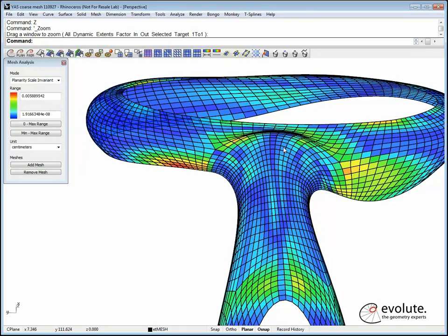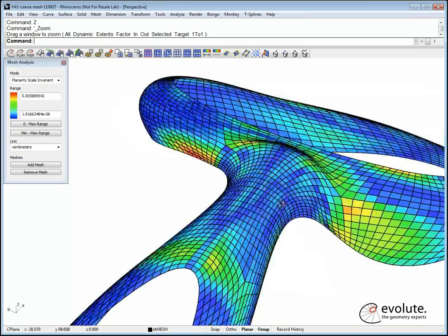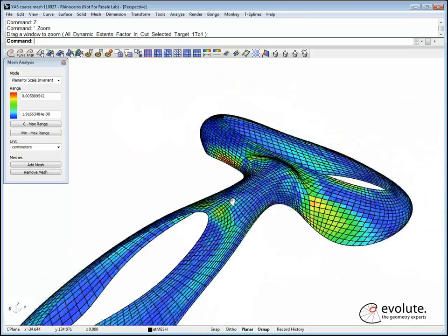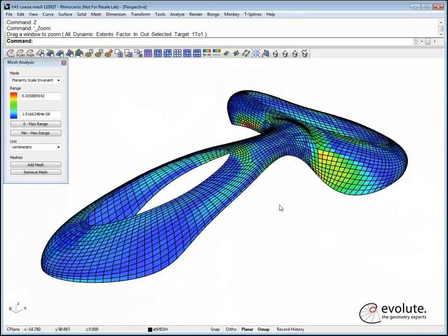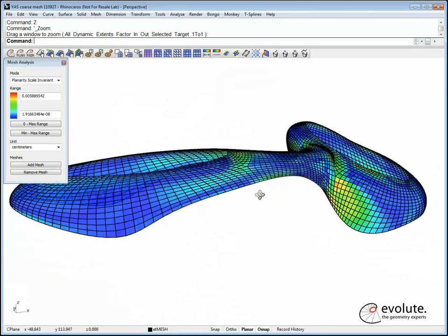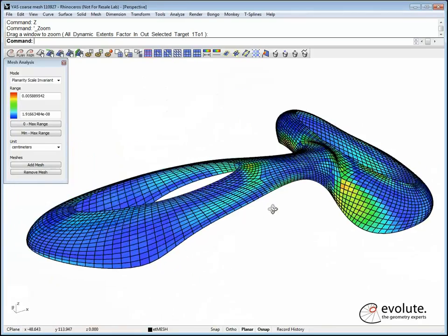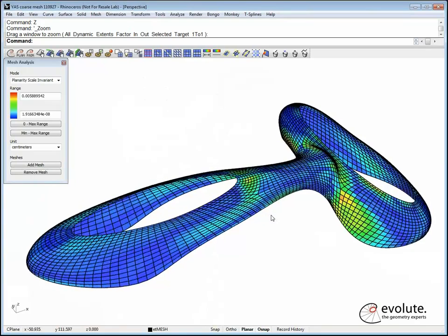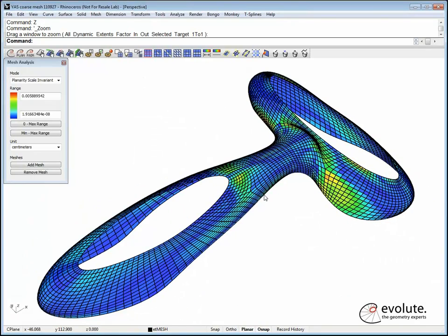This is a really good way to tell if your panel layout is really suited to get really flat quads everywhere on your surface. But of course, we do have them on most of the surface here, and this is what the plugin is for, to improve the results and to lower the costs of construction by optimizing this grid shell, this panel layout.